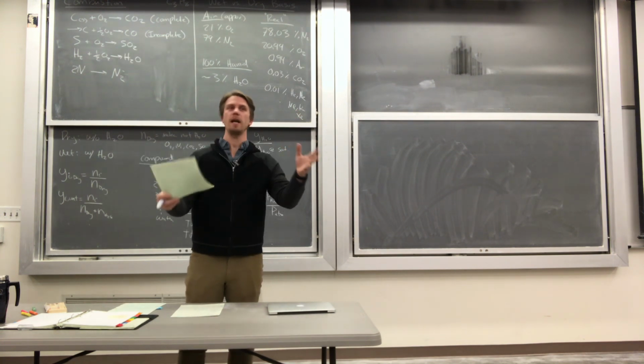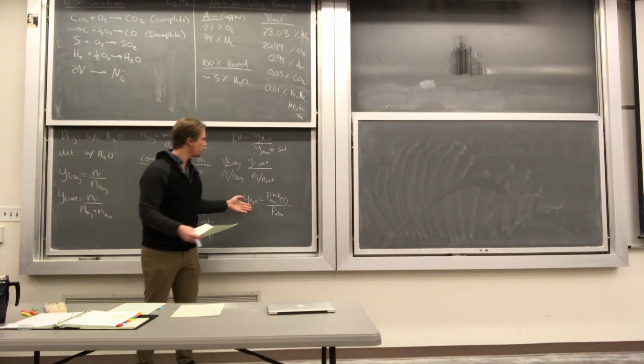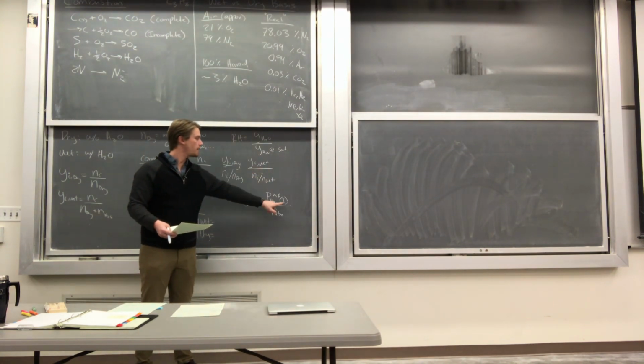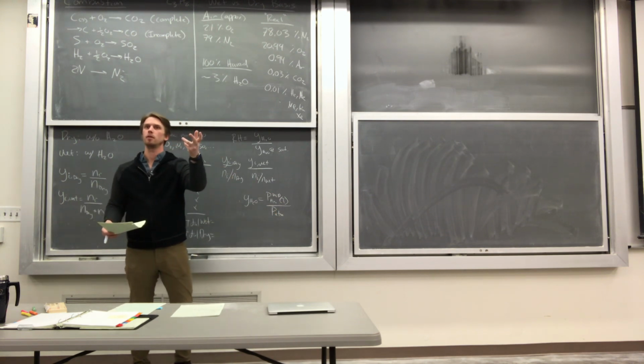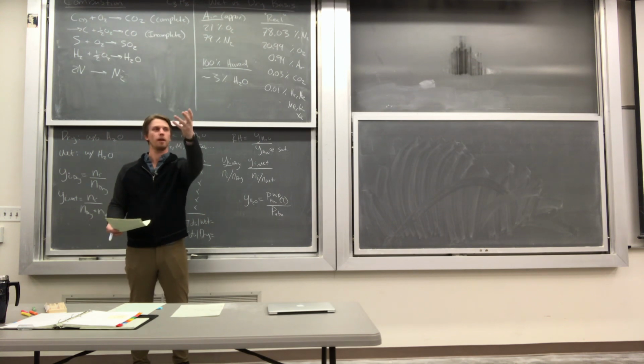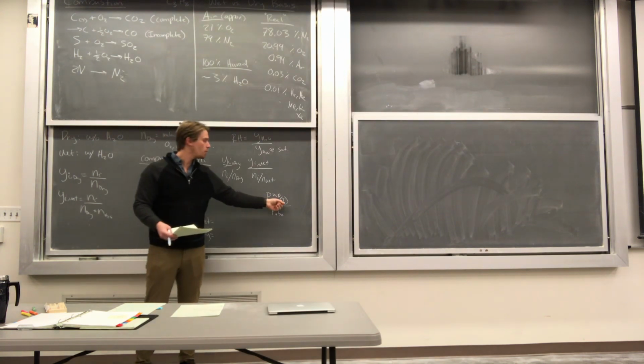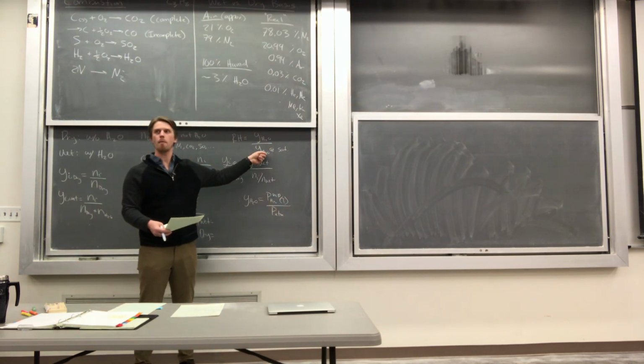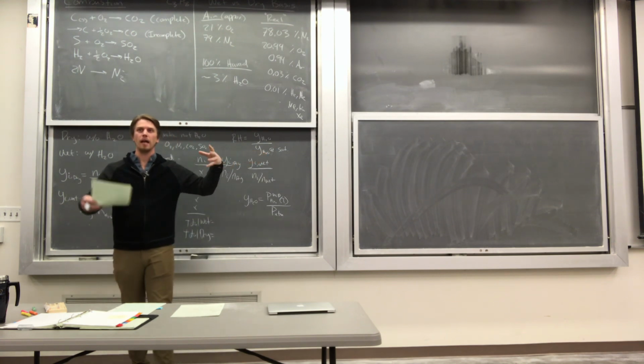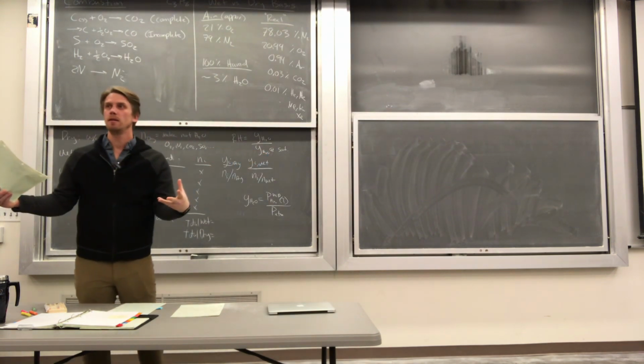So that hot, humid air is at a relative humidity of 100% based on the temperature that the air picked up all that water. If it gets pushed up into the atmosphere or into colder air, or if air from Canada comes and meets it and chills it out, that lowers the vapor pressure of water, which means that it lowers the maximum amount of water that can be in the air. So then that means that your air is now supersaturated.